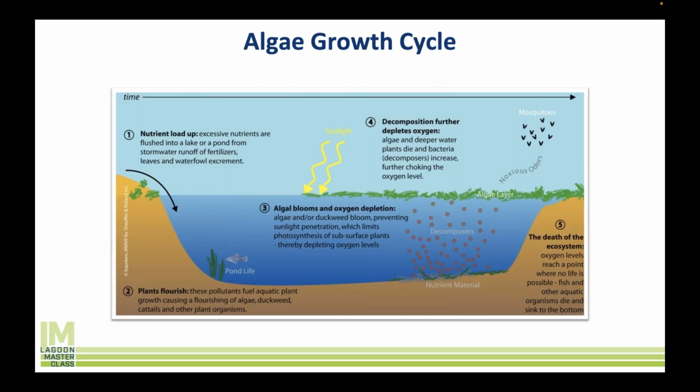And so this can create a layer of really good dissolved oxygen at the surface because the algae is photosynthesizing, it is taking carbon dioxide and converting it to oxygen, right? But it also can cause an oxygen-deprived layer at the bottom, right? It can starve the rest of your pond of oxygen, which will create more of an anaerobic digestion environment that is breaking down the sludge, creating H2S and things like that, and doing so very slowly.